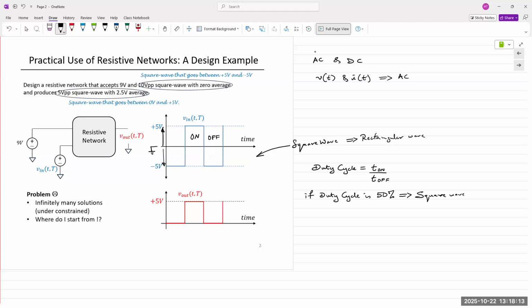Does that make sense to everyone? Right. Now, if you want to change the value of this reference level, either from 0 you go in the positive direction, or from 0 you go in the negative direction. Meaning you're taking the middle point of that waveform and shifting it above 0 or below 0. That process is known as clamping. You're clamping the waveform at a particular DC level.